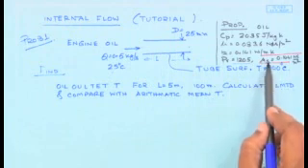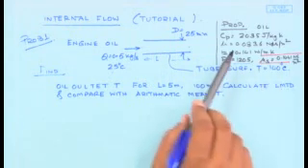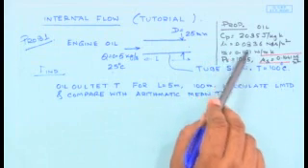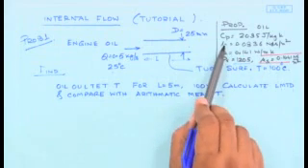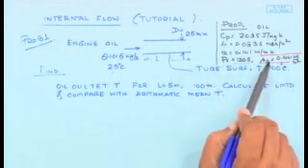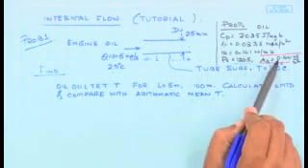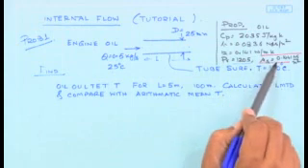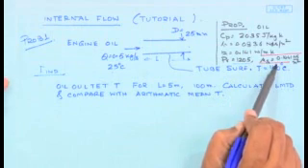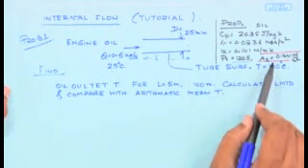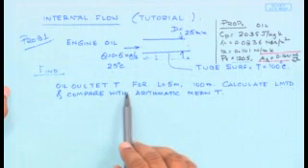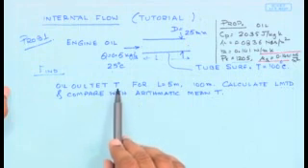So mu at the surface temperature is provided, and see how much of a difference there is between the mu at the bulk temperature and the mu at the surface temperature. So there is a significant variation in viscosity. So a viscosity correction factor must be employed in order to obtain a correct value of the heat transfer coefficient or the value of the temperature and so on.